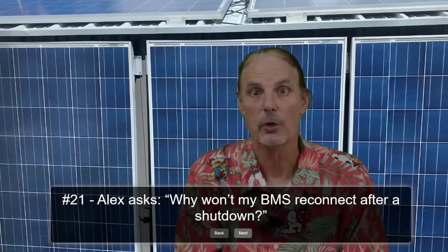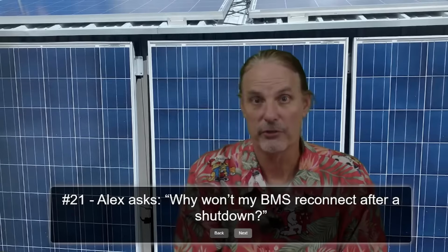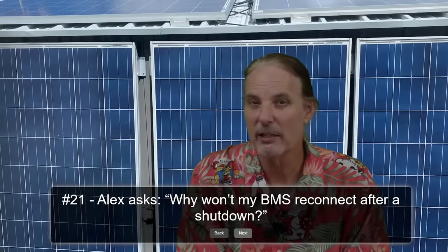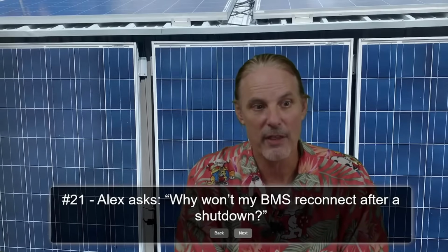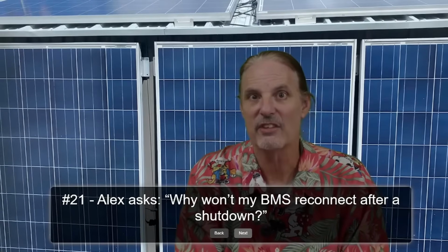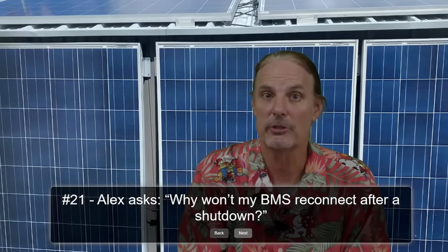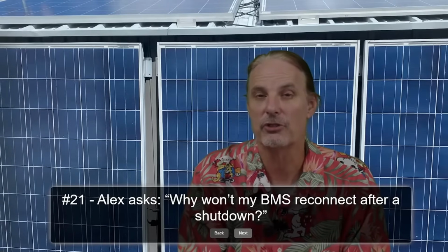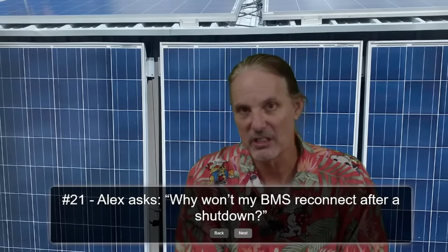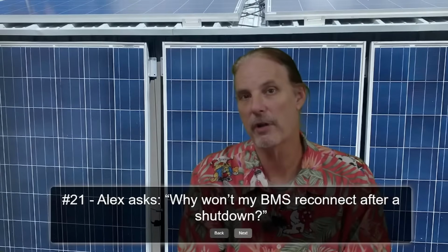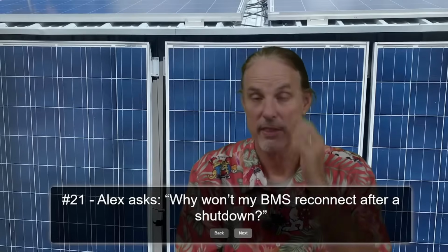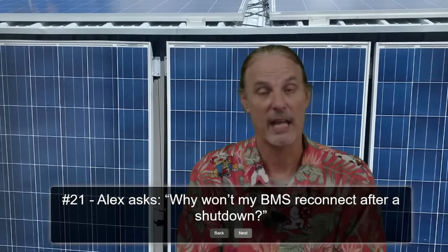Most likely your configuration for your inverter, if it's an all-in-one, or for your charge controller, is configured wrong to not automatically recover, and that would be why it's done that. That's what I normally see, that it's not getting that trickle charge, which re-enables the BMS and turns it back on after it's shut down from discharging. Most BMSs these days, and you'll see from the video that I produce that comes out the next day or two from the Lead Time battery, the 24 volt one, it had exactly the same thing.